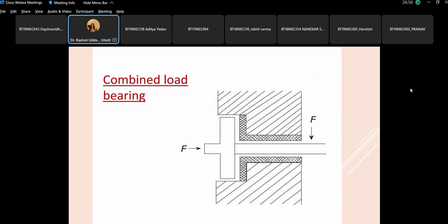So as I told you, after we finish with this bearing and wire rope, next month when you will be physically here, we'll be solving assembly problems. And the moment you are designing a shaft which is carrying a helical gear, you have to design the bearing which can take care of axial as well as radial loads.